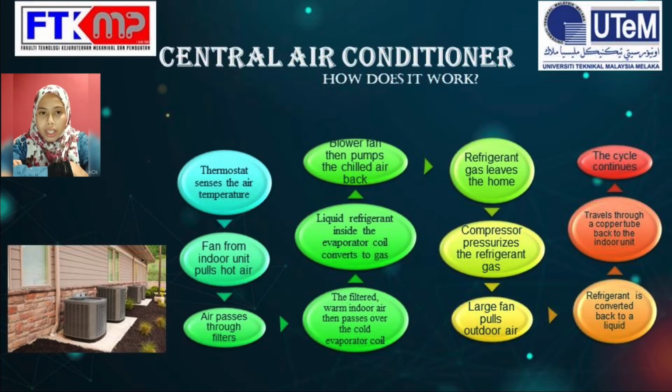The cooling process starts when the thermostat senses the air temperature needs to be lowered and sends a signal to the air conditioning system components both inside and outside the home to start running. The fan from the indoor unit pulls hot air from inside the home through return air ducts. This air passes through a filter where dust, lint and other airborne particles are collected.